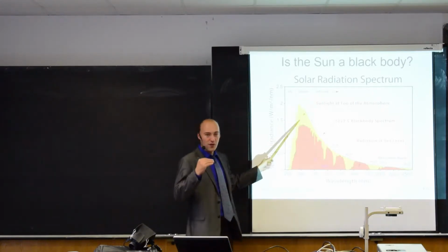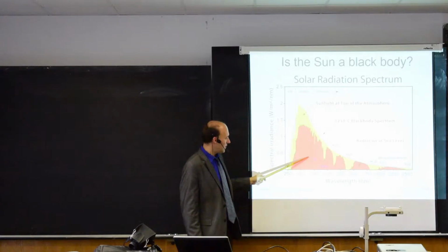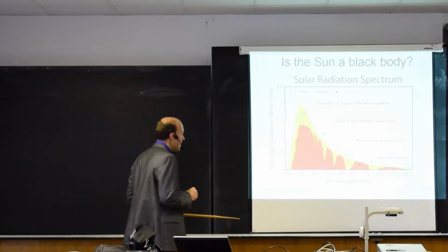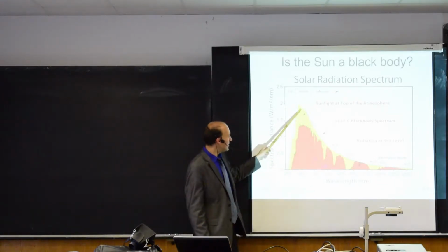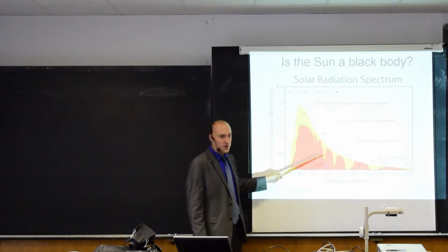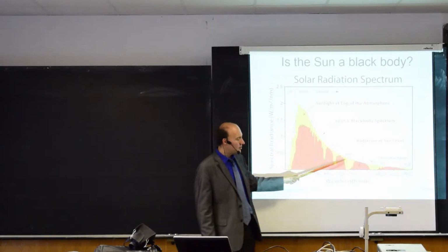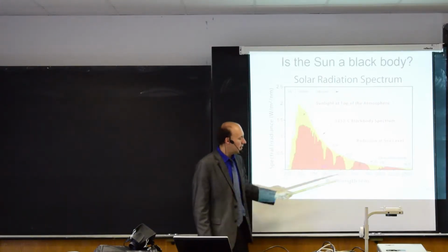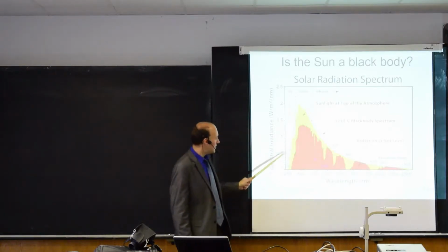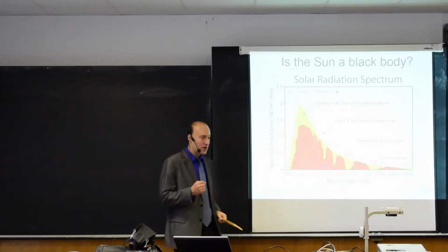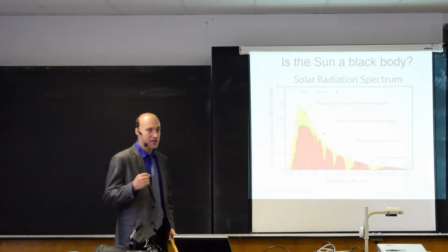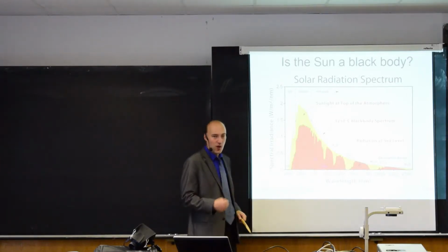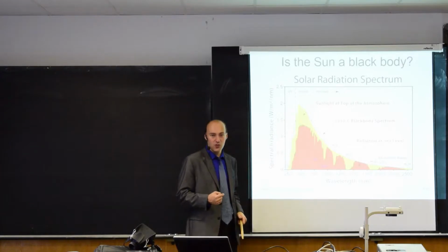The yellow is on top of the atmosphere. The red color here is the radiation at sea level. So here we can see the absorption in the atmosphere. All this is absorbed in the atmosphere, and here we can see individual components responsible for that. So here oxygen, water, and carbon dioxide. So this demonstrates to us that if we would like to measure the temperature over long distances, we need to take absorption into consideration, because otherwise I would read a different temperature than would correspond to reality.